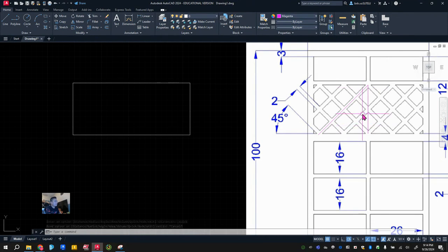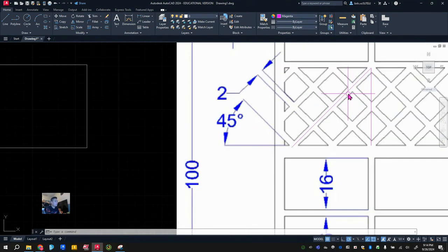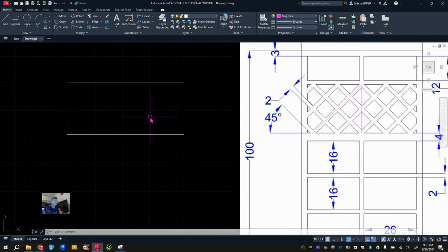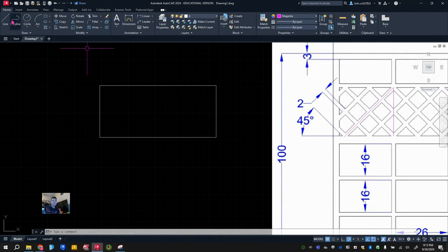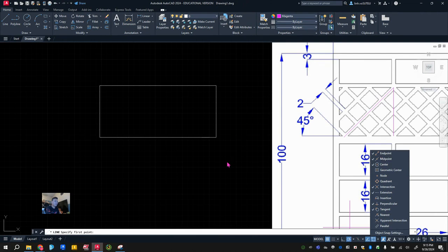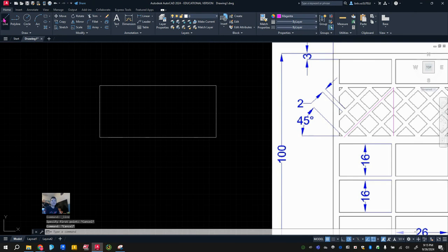So we're going to take a look at that and see what we're going to do. The only thing that's missing is the length, the dimension of each of this side of the shape. All right. So what we're going to do is we're going to try to figure out that information, and all we have to do is click on line and make sure that down here on your snap, make sure that's midpoint turn on. Now, if your midpoint don't turn on, you can just hit the control and right click, then you can select the midpoint. Okay. But I would like for that to turn on. So I'm going to go to line. You can see the triangle. I'm going to go ahead and construct it in that way. Hit enter again. I'm going to do this right there.